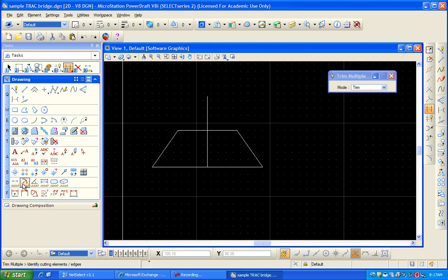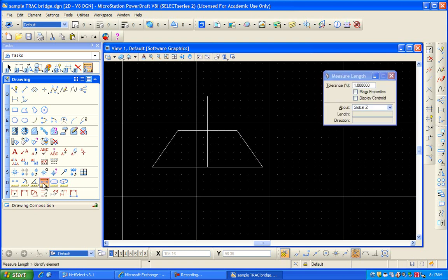You can measure between points, or you can measure the element. Let's measure the element, and we'll select the top there, and it does in fact say that this is 8 inches long, so that worked out fine. Last thing I'm going to do here for my side view is I don't need my center reference part anymore, so I'm going to go ahead and delete that.